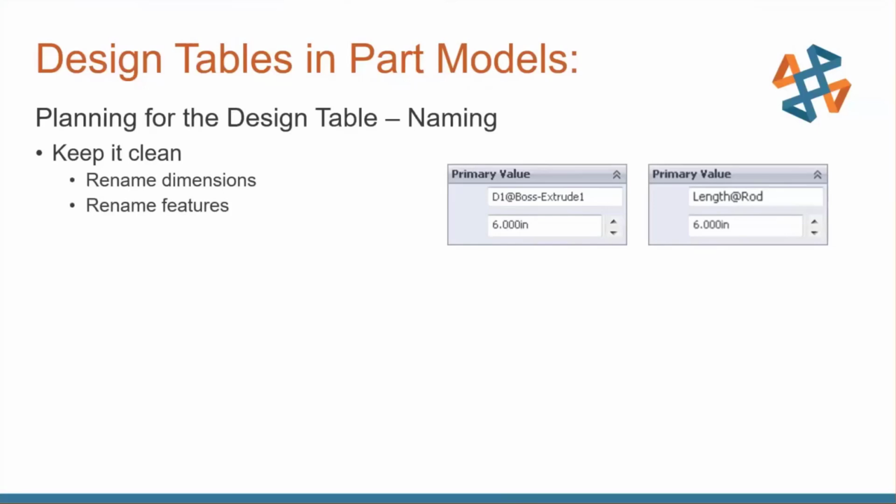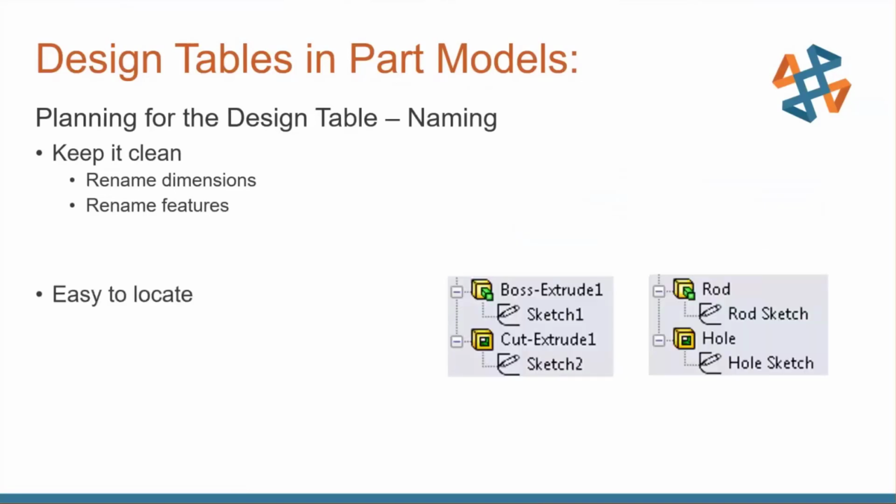I know I've done it, deleted a feature that I thought was insignificant, but it was very, very important. Got the tree blown up. Thankfully, I could undo back to safety. But if you just rename a couple of features, they're easy to locate in the tree. You can use the tree filters to find things effortlessly, but also make sure that you don't accidentally remove one of those features. That's extremely critical. Now, for renaming, it's left click, pause, left click, or you can select and use the F2 key on your keyboard, kind of the universal Windows hotkey to rename, works just as well.